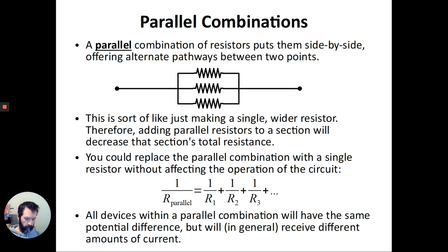All right, so this is another way that you can combine objects in a circuit, and we did not really study this before we had to close down. This is called a parallel combination, because instead of putting them one after another, they're all side by side. So again, if you come in on the left, current flows until it reaches this intersection, but then it can split up. There are 3 different pathways provided. Those pathways have to recombine later, and then they go off.